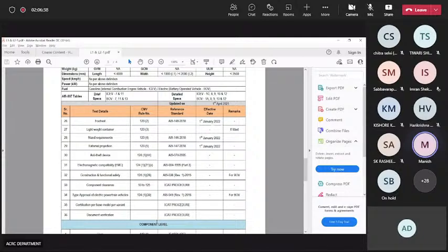And finally, all the documents will be compiled for your part level and vehicle level tests, and you will be issued a certificate. This whole process, vehicle level will take 3 months, and part level will take another 1 to, let's say, 3 months. It's a 5 to 6 month process, and it costs around: part level will cost you 50 lakh, vehicle level will cost you 15 lakh, 50 plus 15. This is the cost with any vehicle certification agency, whether it's ICAT or ARAI.